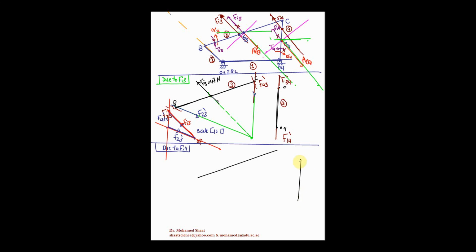In this way. So in such a way that this is point C, this is going to be point O4, and this definitely is going to be point C, this is going to be point B. Make sense? Then what? For link number 3, just two force members. So skip this one till the end and just specify the direction and draw the force F14.